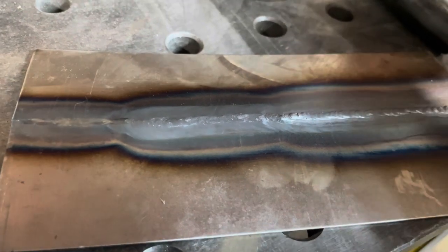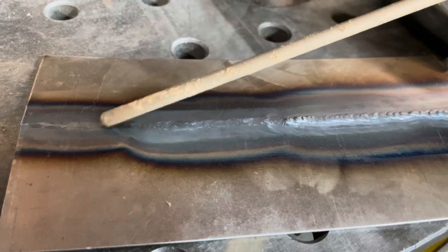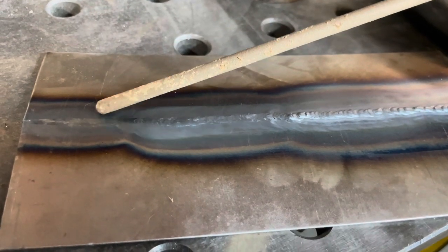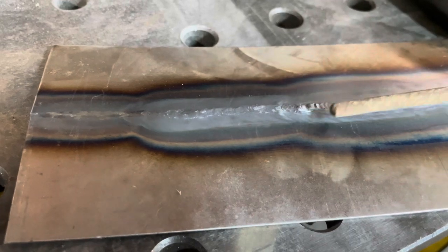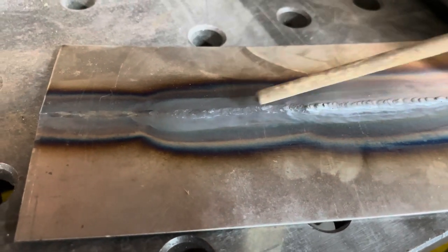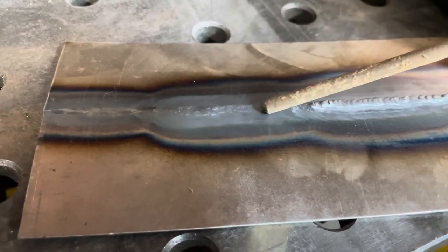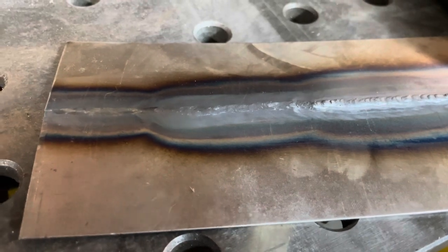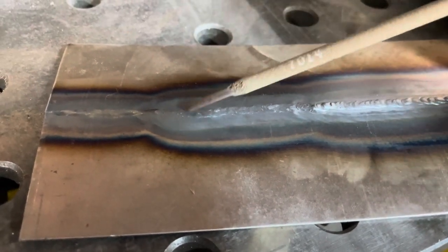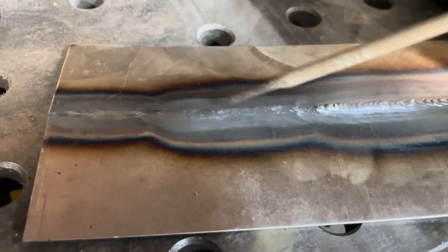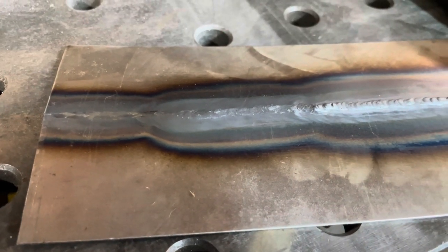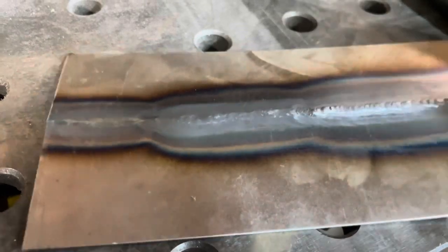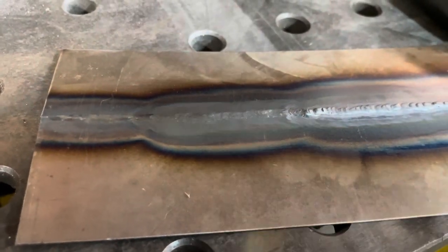But once again, it's a prime example of heat conductivity because it conducted the heat away. The longer the dwell time I had, the more it could pull the heat. And adding that cold filler into that liquid puddle changed the temperature, so I had to give it more time in order to allow it to get to that molten state and completely fuse. So I'm going to let this cool off for a minute, we'll move to the post dolly, and we'll get her back down flat.